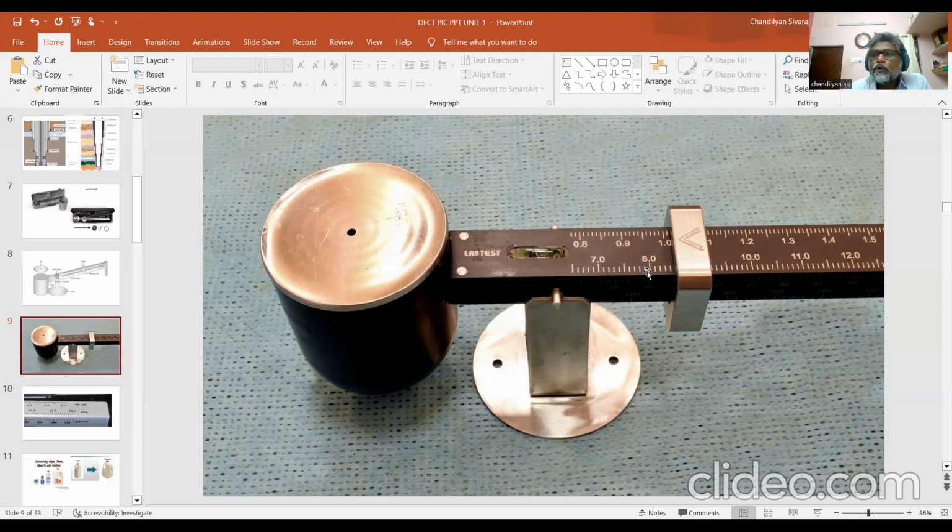Until then, you can slide, play, and get things done and see what is the correct value for mud density. For water, it is going to be 8.3, and for specific gravity, it will be 1. So this is the way we can measure the mud density.